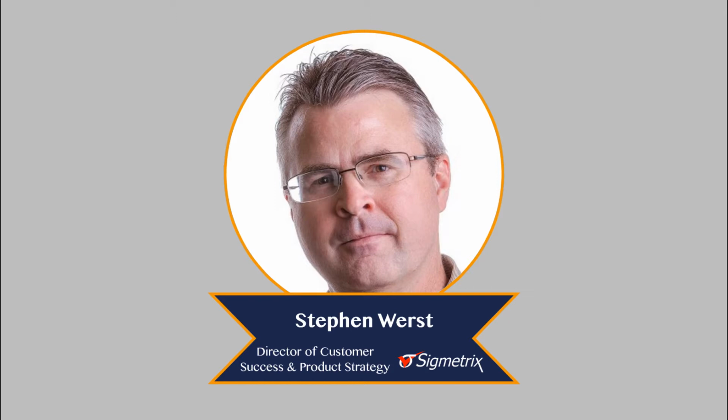Ryan, you mentioned the term qualify a datum. Basically what we're talking about here is making sure that the characteristics of that feature are defined as needed. With a primary datum, typically it's the form. If you're dealing with a secondary, you qualify it with an orientation or perhaps position, depending upon how it relates to the primary. Just making sure that everything is specified for that feature that needs to be. So the term qualifying the datum just means making sure that the appropriate tolerances have been applied to the datum.